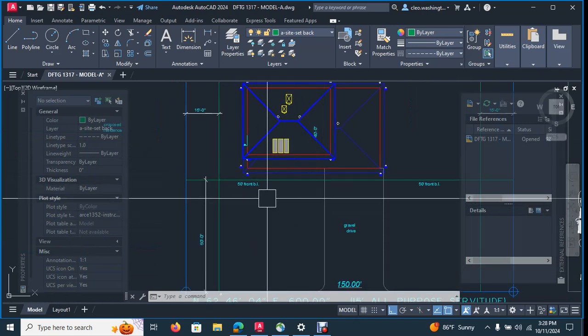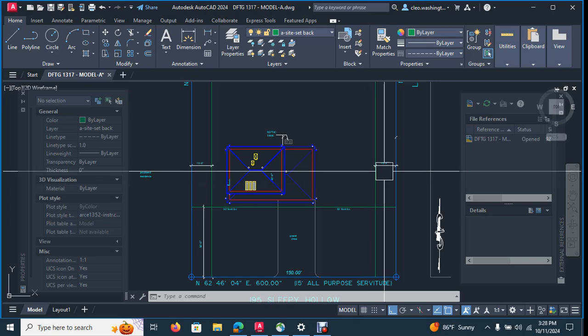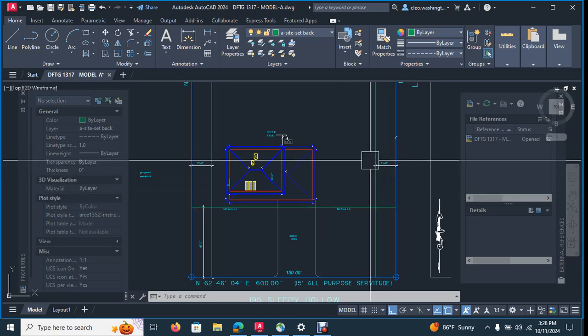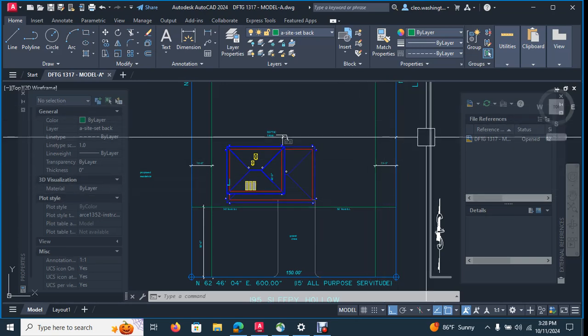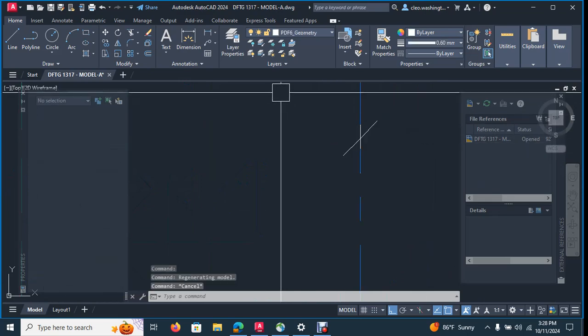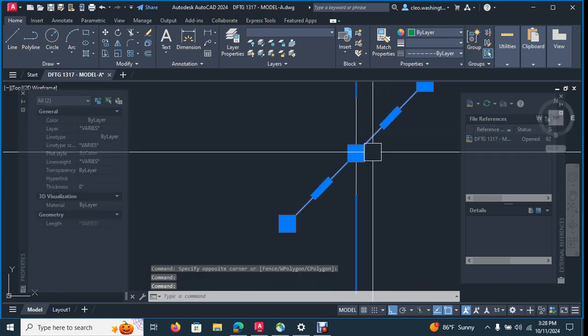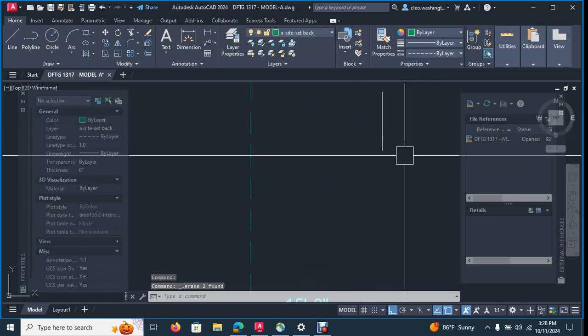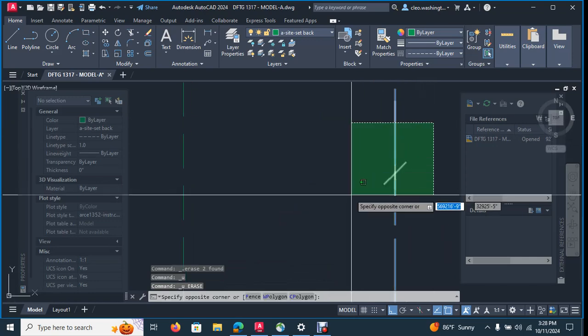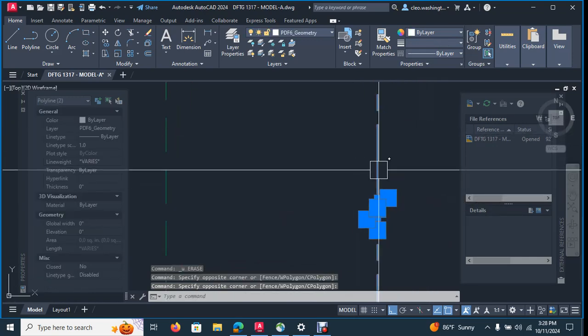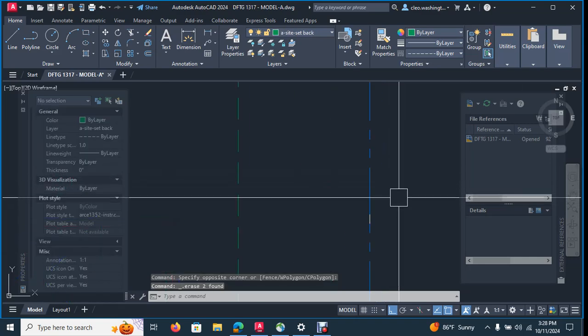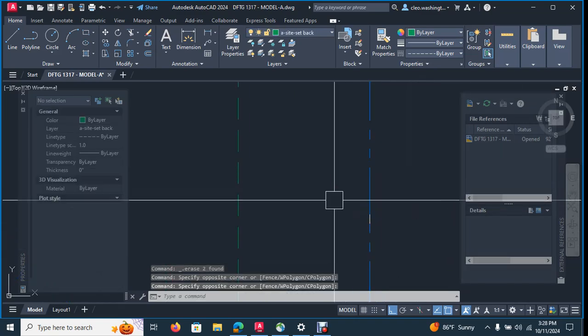Now, what we need to do is show what the setbacks are. We need to show dimensions, okay? Where is our building from the actual property line? So we need to add some dimensions on the site plan, the ones we just deleted. We don't need to actually show all of them, but we need to show some dimensions that will tell the contractor, hey, this is where our building is. This is how you start your work, okay?